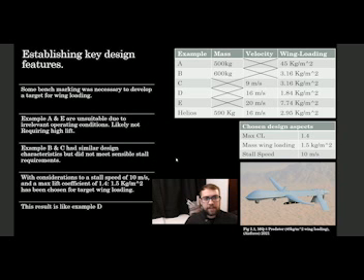The first key design feature to establish was wing loading. By benchmarking, or comparing previous designs to current requirements, it appeared that example A and E in the table here are unsuitable for the design. They are likely either low altitude aircraft or high velocity aircraft. Air density is higher at low altitudes, which would increase lift, and high speed aircraft have more effective lift if you consider the lift equation, and less concern for stall velocity.